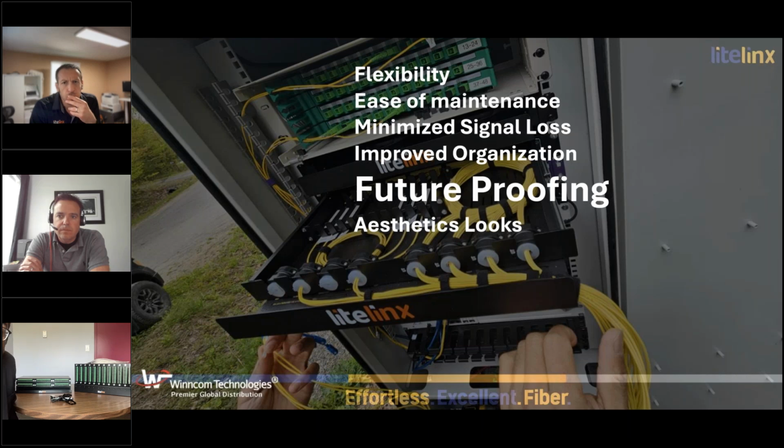The second thing we improved on is, let's say right now we are doing a 1:2 split, a 1:4 split in that box you're seeing right now on Alex's screen. If you want to change the ratio to, let's say, 1:8 in that box, it's a very easy solution. For each port, you just remove that splitter and put a new splitter there, and you are up and running again, in a very clean way. Every cable has its own path to follow. Every cable has its own place to go.